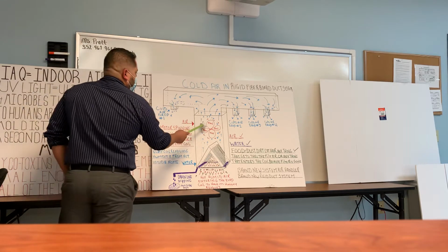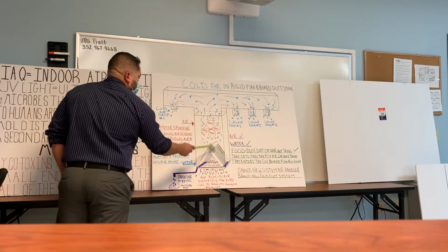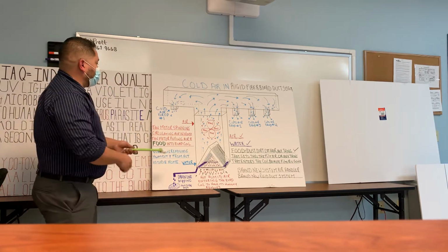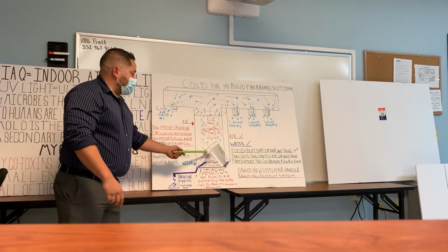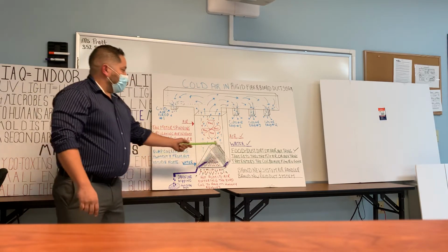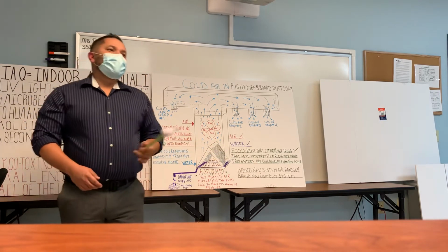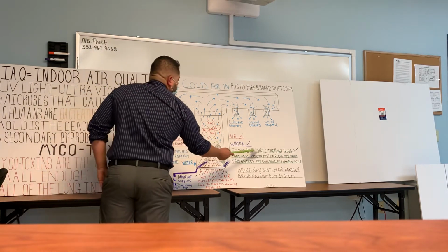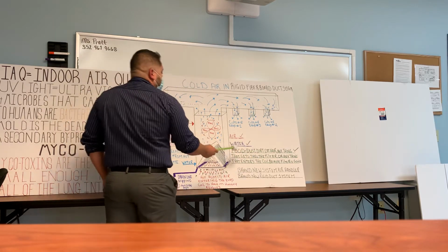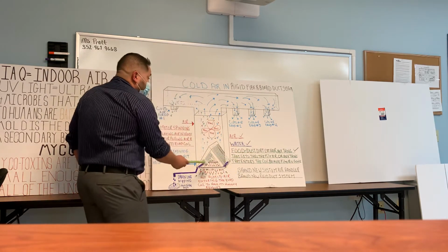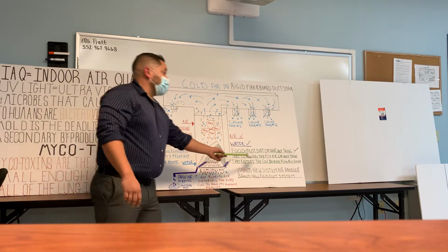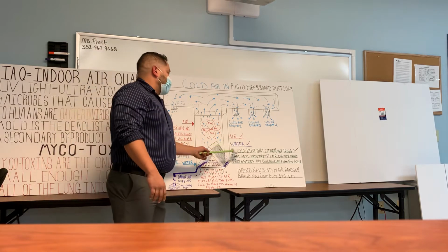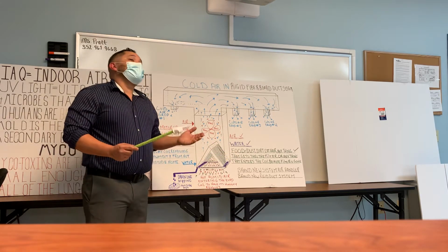This air handler is basically a box with a fan and the coil. The fan motor is spinning, circulating the air in the home, and pulling air and food into the evaporator coil. So we have air, we have water. Well, what's food? Food is very easy to get into the air conditioner. Food is anything that gets through the filter. Dust, dirt, cat hair, pet dander, anything that gets through the filter or anything that enters the coil because the filter is gone. So when you have air, water, and food, that's what mold needs to live.